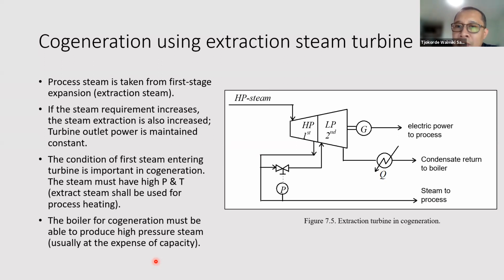And if that heat transfer media is saturated steam, then its saturation temperature will have to be some degrees Celsius higher than 100. Now, how much higher? 5 degrees, 10 degrees, 15 degrees? So you can easily see that this immediately becomes an open-ended problem. And this is what the typical job of engineers is.